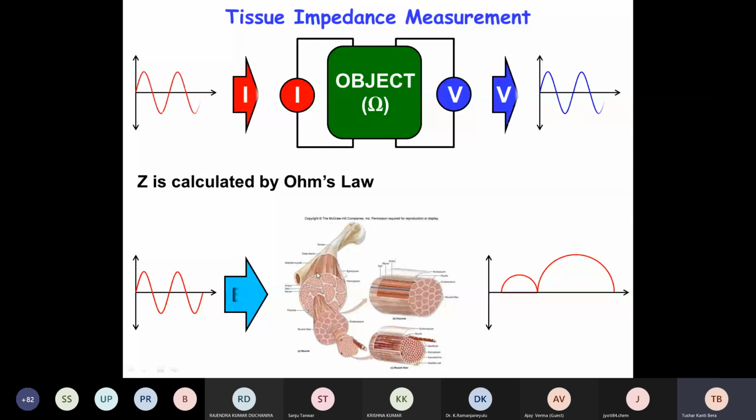Among the non-destructive testing methods, electrical impedance spectroscopy, or electrical impedance methods, are found to be fast, low-cost, and portable techniques, which can be applied for measuring electrical impedance to extract material property information. Whenever photovoltaic technology develops a photovoltaic cell, several parameters are measured with the help of electrical impedance spectroscopy. The photovoltaic cell is taken as a sample, and 4-electrode or 2-electrode method based impedance is measured at different frequencies.